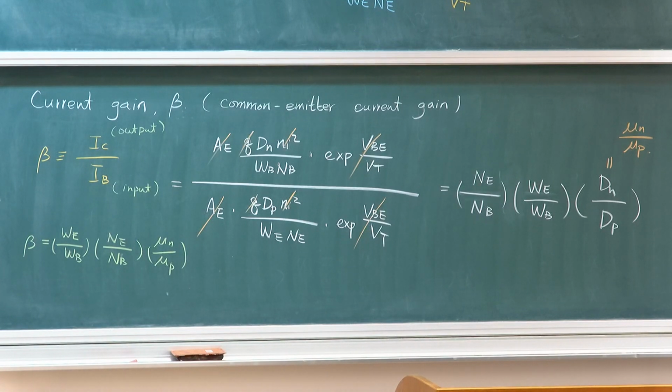If you look at it from an engineering point of view, what can be manipulated most? Do I have a lot of room in engineering the base and emitter width? I make the base very narrow, but the emitter depth very large. So how do I make this ratio high? Or is it possible to make it high? Typically, this is the ideal characteristic.